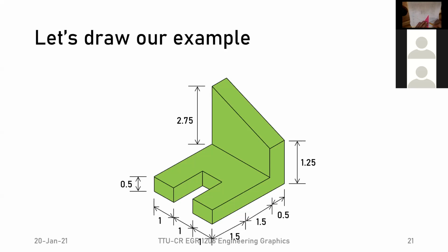So here we want to do a dashed line. And we'll talk about rules for these dashed lines, but just to begin with, we always want to have our dashed lines start and end at an actual line. So we have this little dashed line. Especially if these are smaller, then it's sometimes difficult to make these lines nice and evenly spaced and still be dashed. All right, but let's not forget to erase our couple construction lines here.